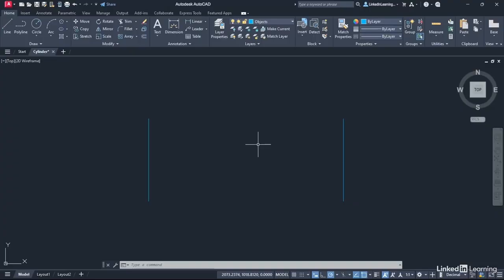To do this, we're going to create an isometric representation of basically a little flat cylinder disc. And it's not going to take long. The ellipse command makes it very, very easy to create it. So we're going to create an ellipse and then an elliptical arc. So we go up to the Draw panel on the Home tab on the ribbon again. You can see on this flyout here, we've got Center, Axis End, and Elliptical Arc.